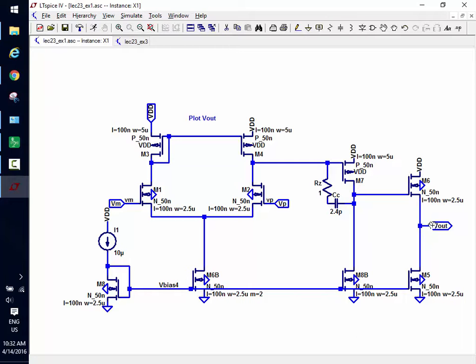What about the maximum value? What's the maximum output? So the input limits the output swing for linearity because I can't drive the input below VGS plus VDS sat. Anybody unclear about that? What about the output? How high can the output go? Well, I know this guy can go pretty close to VDD. Does everybody follow that? We derived that last time.